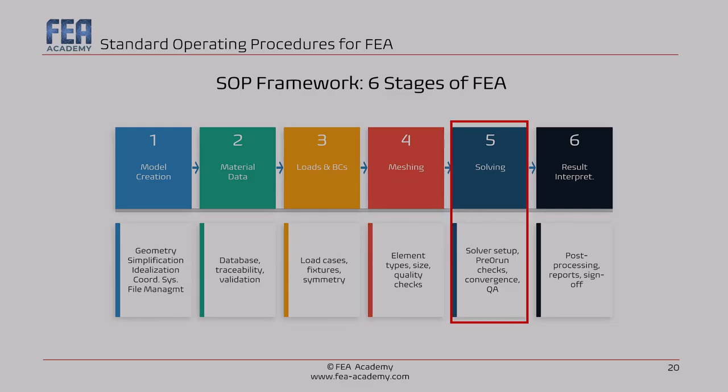Stage 5, the solving. This is where the numerics happen. Most engineers treat the solver as a black box, okay? Press go, get results. SOPs for the solving stage ensure you go in with a pre-flight checklist and that you monitor for suspicious behavior and come out with a verified set of results before you even look at stresses.